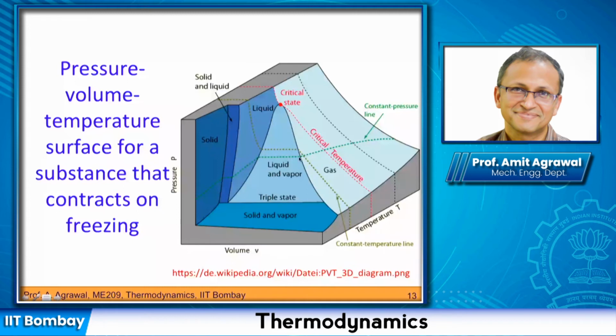And now you have introduced the quality. You can see that the quality is 1 here. And now the quality is going to reduce continuously as you move along this line. Okay. And then at this point, your quality will become 0. You essentially convert everything, all that entire mass that you had of vapor has now been converted into a liquid. So quality is now 0.